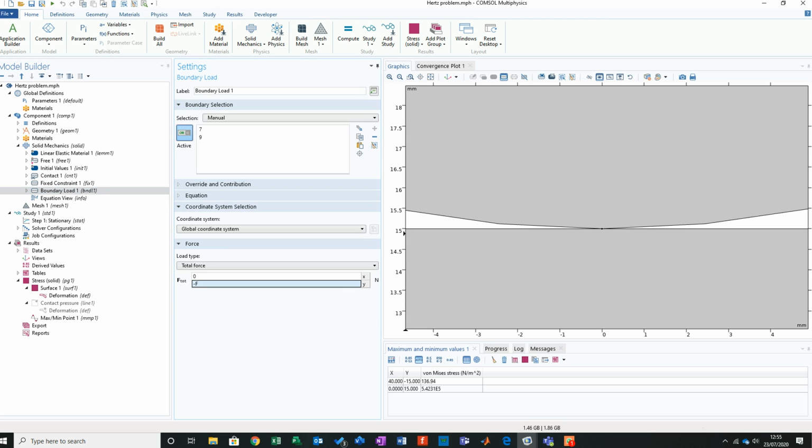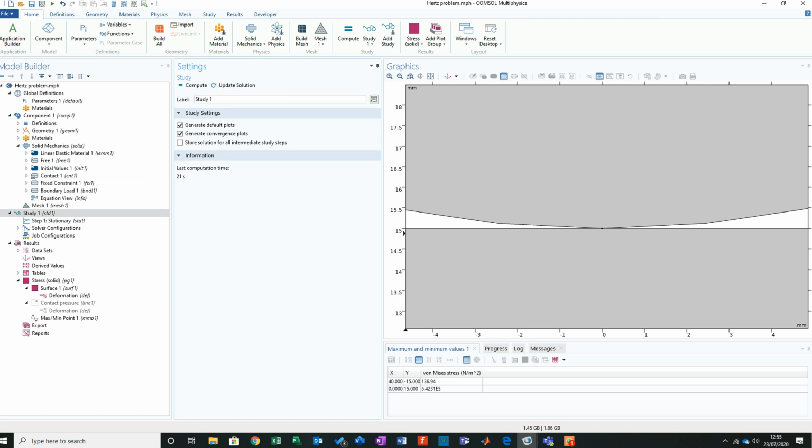And you look there, I did this. This was my mistake. See how we've got minus F? That just continues that force continuously. So what I want to do is an incremental build. So I'm going to go open brackets, para, multiplied by my force. And then I'm going to come back and run it again.